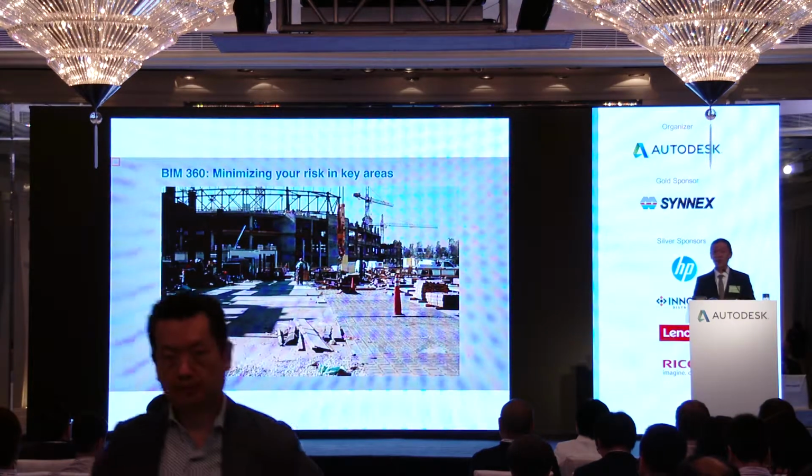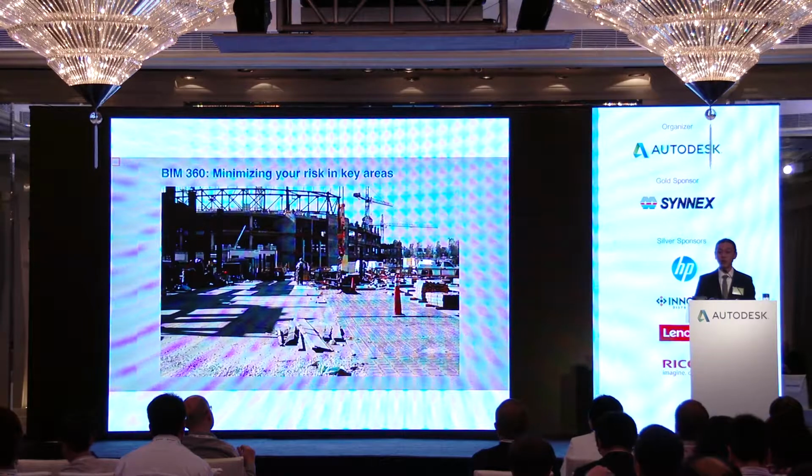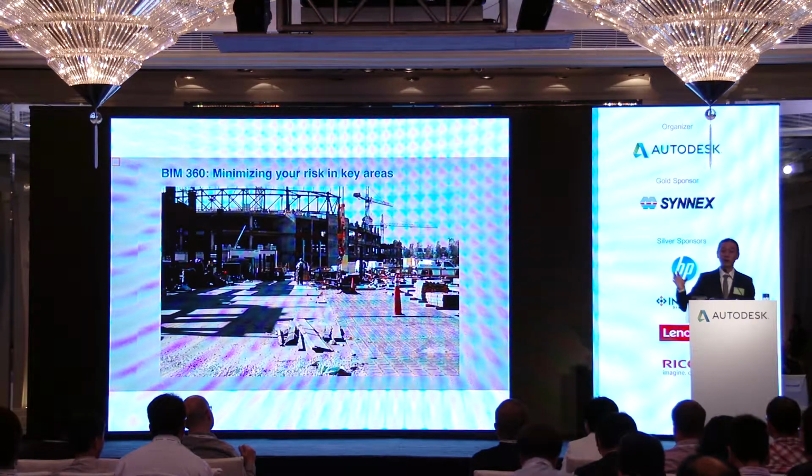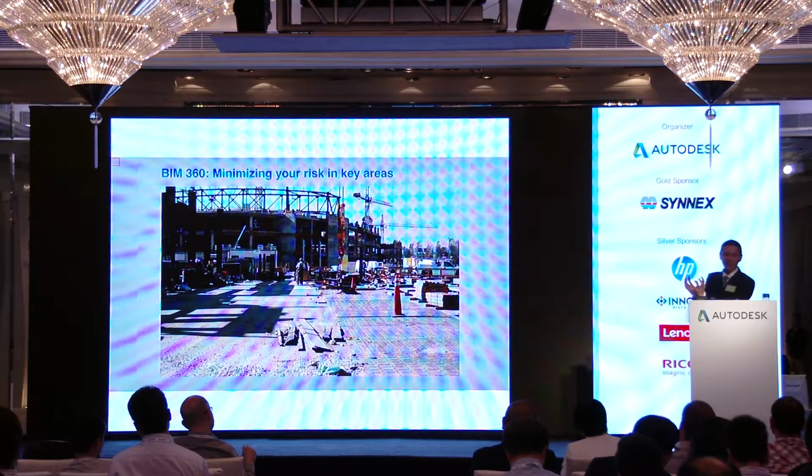And it definitely minimizes a lot of risk because you can tell it's going to be 10,000 clashes, and you know where the clashes are because all the orange dots are focusing on that area. Don't look at each clash on its own. Look at it as a whole picture of where all the clashes are generated. It shows you exactly where they are.